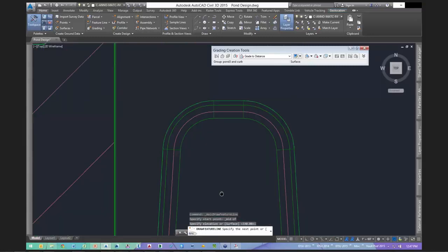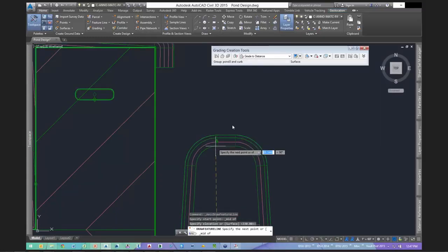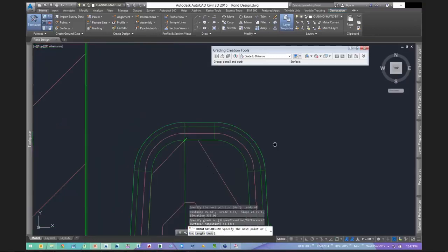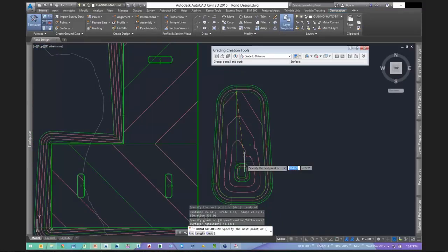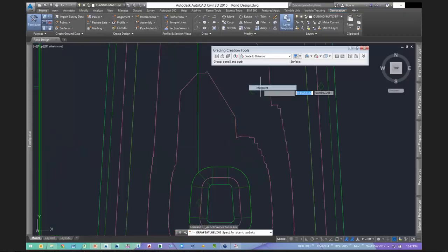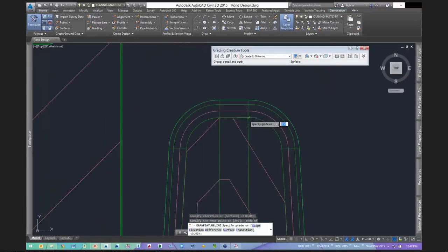And then come up here and we'll do a midpoint snap again. I take it back. We're going to go right up to this point right here. So it reads that elevation as well. Okay. And because I drew that right in the infill, it's going to triangulate right to that feature line. So let's draw another one like that. I'll go from the midpoint right here, accept that elevation, and then come right up here to the end point of that original feature line and accept that elevation.